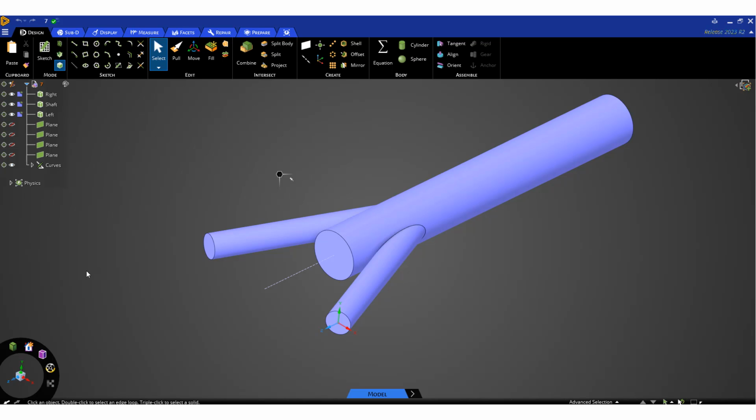water systems, okay, and the difference between pipe flow and this open channel circular flow is that in pipe flow we don't have free surface. This is one very important thing here, but in open channel flow we have a free surface. Another thing is that the flow speeds up in pipe flow by pressure, but here in tunnels and in these open channel circular channels, we usually have the flow speeding up by gravity.